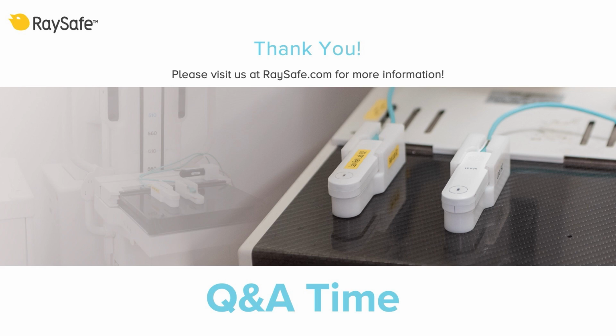What is the recommended calibration interval? Well, calibration always comes down to the user and how much the user actually trusts the instrument. And it may also depend on how you have treated the instrument during calibrations and so on. But we recommend a yearly calibration, which is according to most regulations. But I know there are people sending it in every second year or every third year. It depends on how it's used and how much you trust your readings.